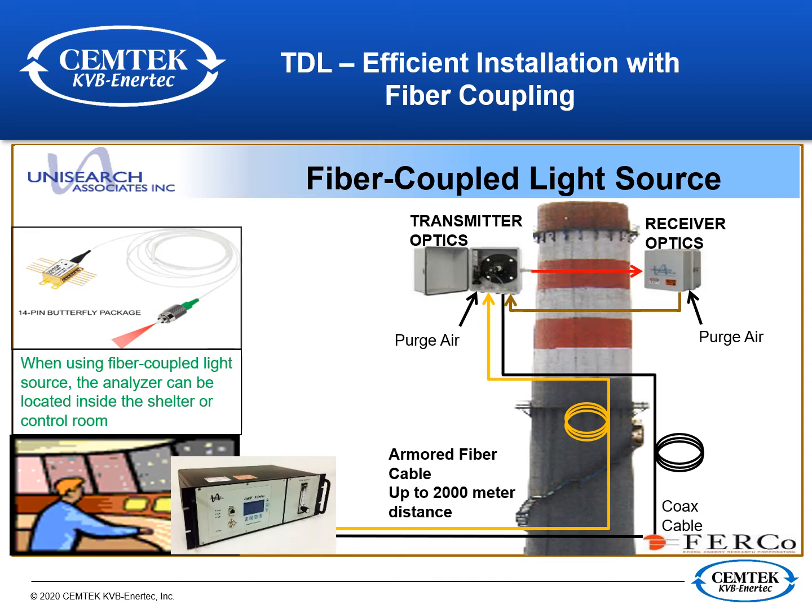All you need to do is hook up fiber optic cable to transmit the laser light source all the way up to the process. The process is going to have a transmitter and also a receiver, and the light source is going to travel across the path. Important to note, in the oil and gas business, they may also have to monitor methane for open path around a plant. This same technology, exactly what I'm telling you, can be applied whether it's open path or on a process.